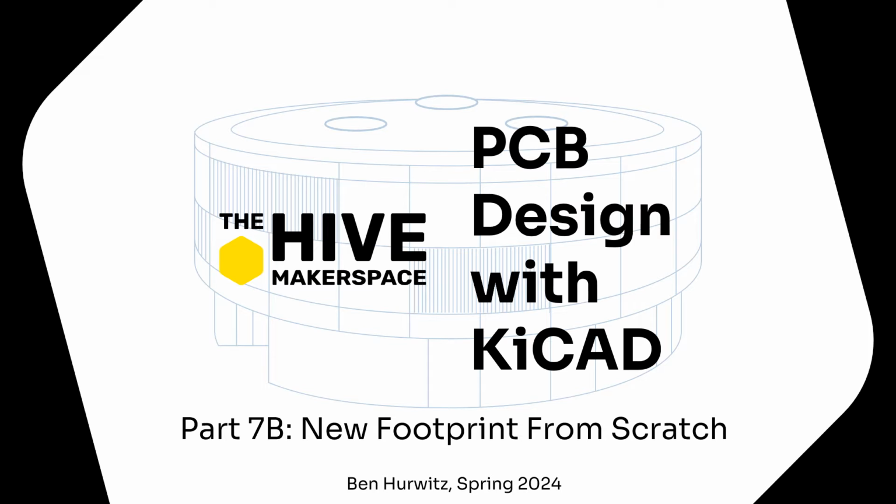In this video, we'll look to generate a custom footprint from scratch for the battery holder, why you should never do it again, and then how to import an online model. This material is, of course, not required for functional design, but it is good design practice for KiCAD, at least, to keep all of your parts in a project-level library. Because this is not directly related to the design flow of the previous videos, I'll make no assumptions about the state of your system or knowledge other than that you've watched part 7A. So I apologize if some of this is repetition for some of you. Let us get started.